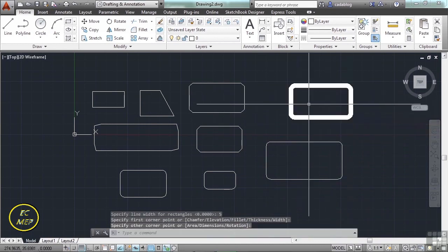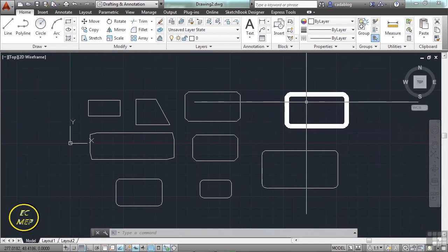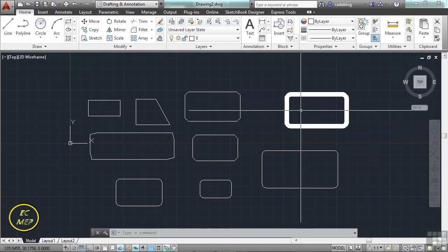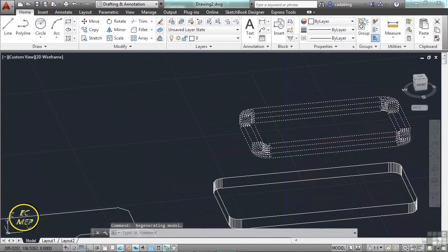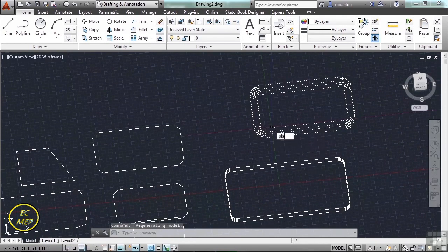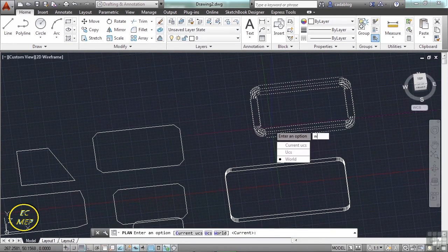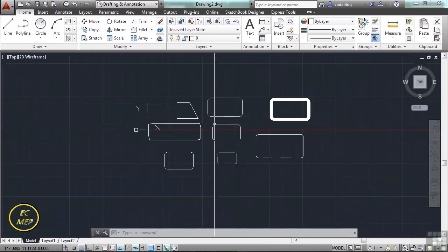Now this is an option that's available in AutoCAD LT. That makes the thickness of the line, the global width, just like a regular polyline of 5 units. Now it's also still set to be thick and at an elevation of 50. Whenever you make one of those changes to the settings of the rectangle command, you have to make sure to set them back until, of course, you close AutoCAD or the file and then reopen it. Then it will be reset to the default settings.